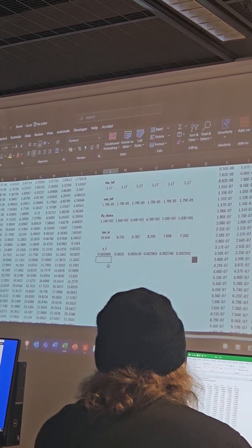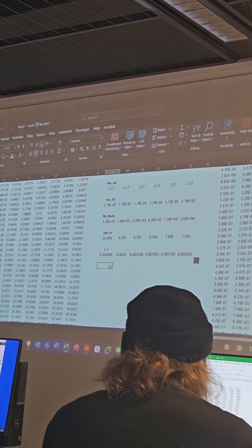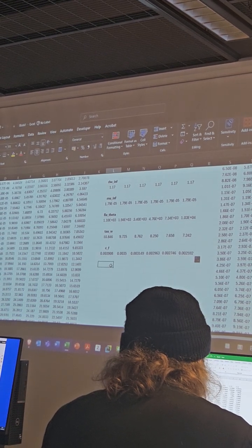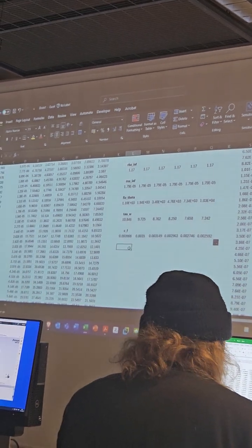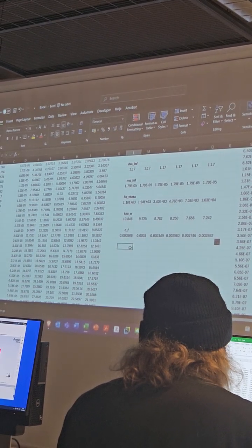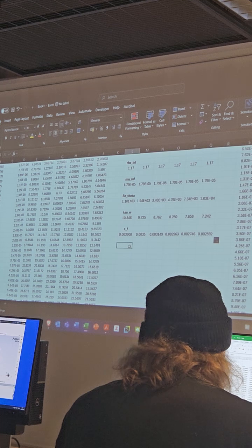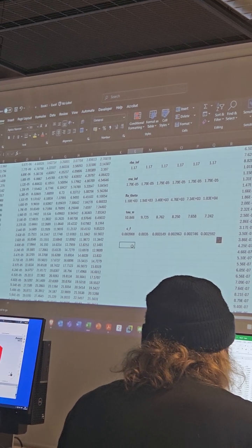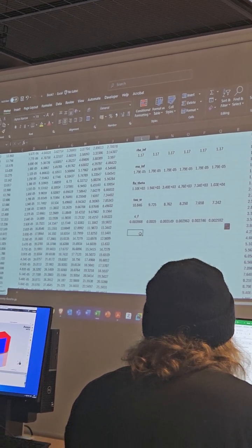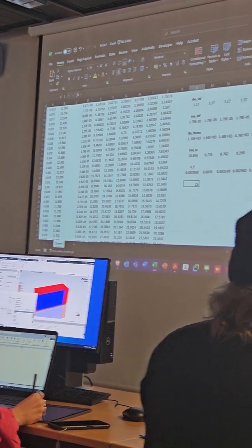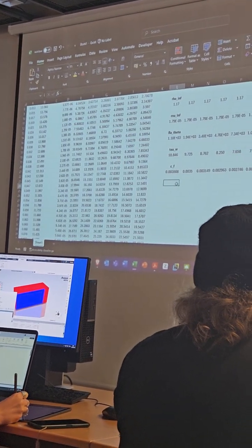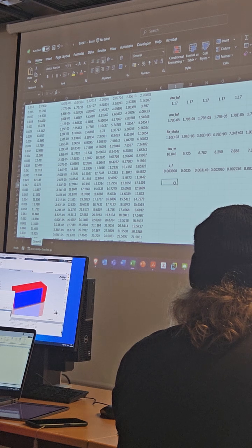In order to do that, we need to calculate the u tau, the friction velocity. The law of the wall means plotting y plus and u plus. For these values, we need the u tau to calculate y plus and u plus. And u tau is given here as the square root of the ratio between the wall shear stress and the density.